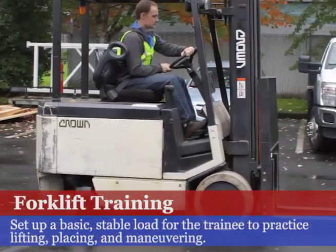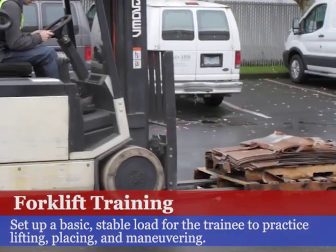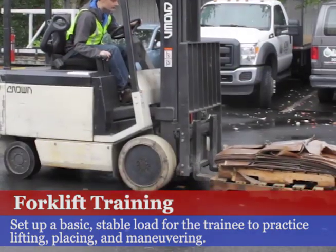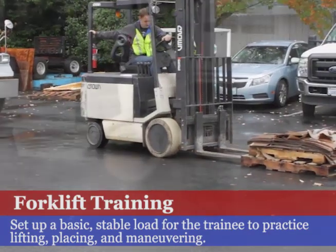Once they are comfortable maneuvering the forklift, give the trainee a practice load to lift. Start with a load that is small and easy to manipulate. Practice engaging, lifting, placing, and disengaging the load. Have the trainee lift the load, and practice driving while carrying the load.